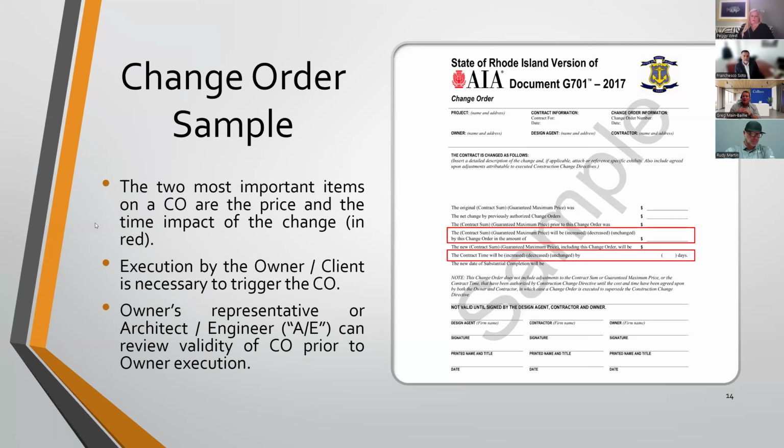And then typically your owner rep is going to say to you, carry a 30, depending on the severity of your building, age, when was the last time you did a repaint. We're going to recommend a certain level of contingency be held below the budget line in reserves in case we do run into an issue with, for instance, the stucco, and it expands from a $100,000 line item to a $200,000 or $300,000 line item. At least your board is still then prepared with a contingency in place to be able to move that project forward and not create any delays or demobilization.